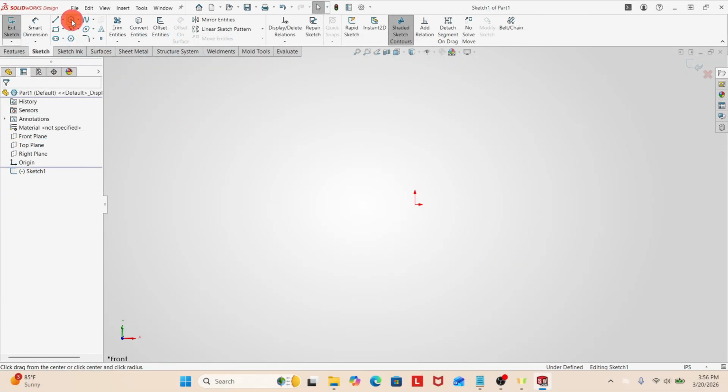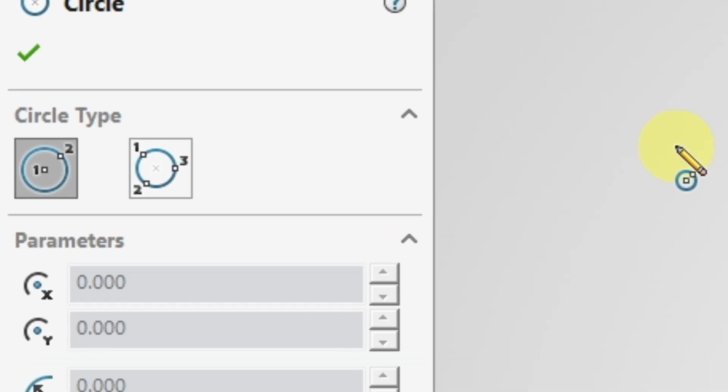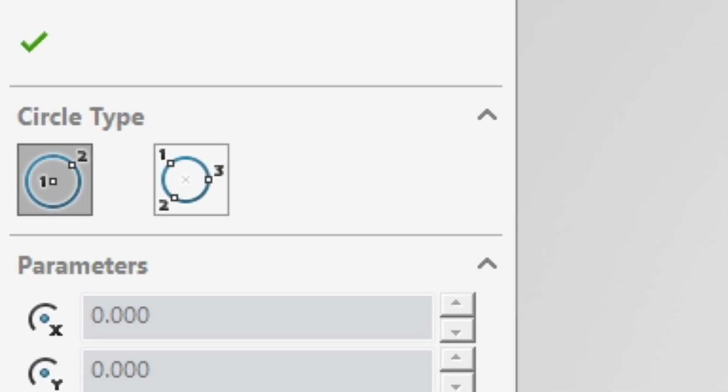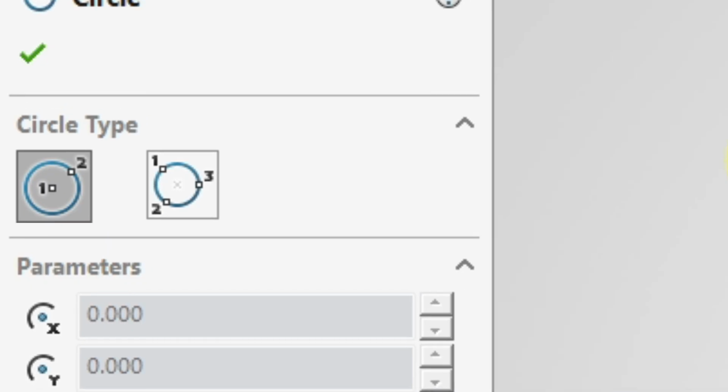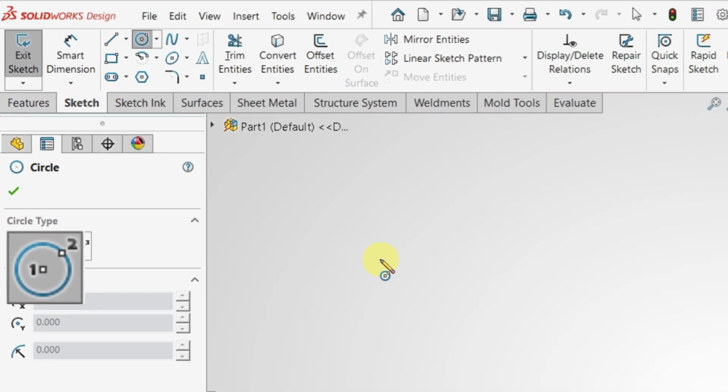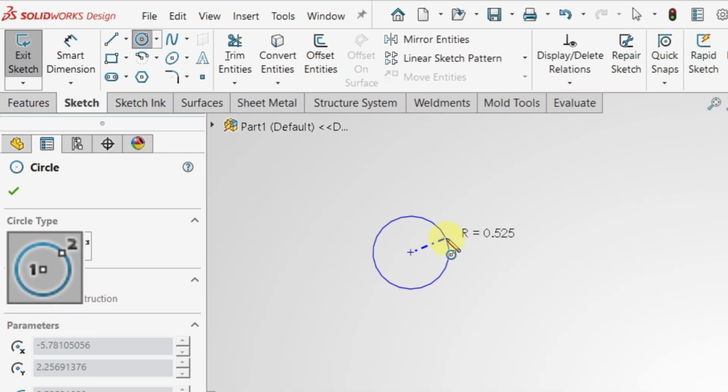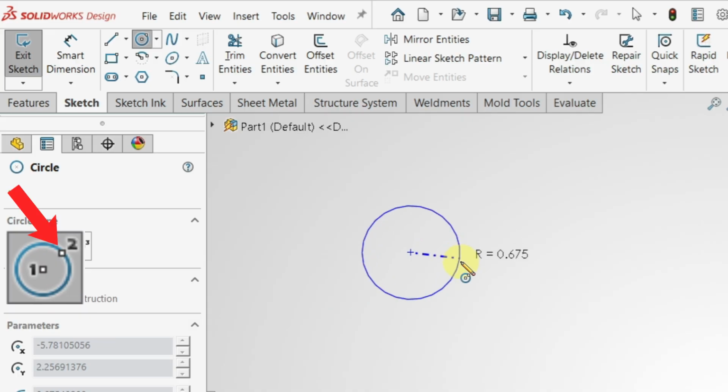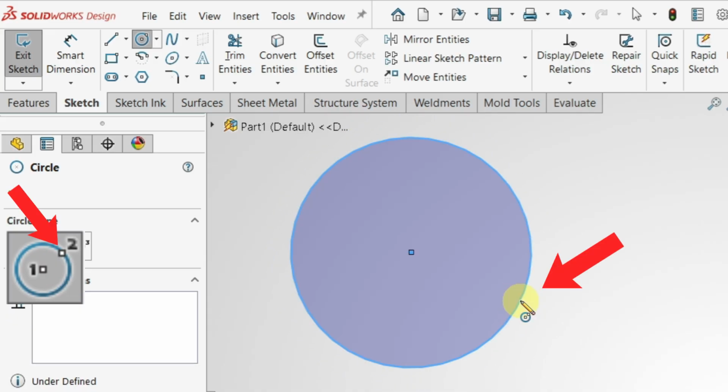Similarly, if we instead use the circle tool, you'll see that there are similar graphics available for us to use as a reference. You can see from this image here that when sketching a circle, wherever our first left click is, will determine the location of the center of the circle, and the second click will determine how big the circle will be. As you can see, these are great references for getting a sense as to how to make each of the different 2D shapes in SolidWorks.